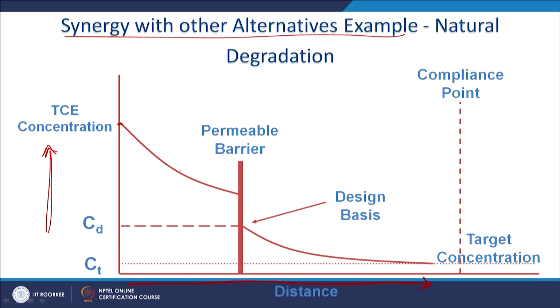Obviously it is going to decrease because of advection and dispersion, you are going to have dilution of the relevant compound, and so if I take the sample along the center line I am going to see a decrease, and also natural attenuation, as in if the microbes have the relevant electron donor here, that should serve the purpose, right.